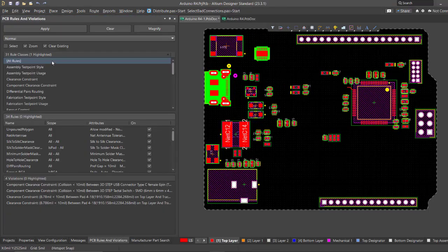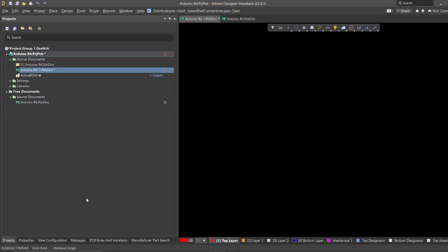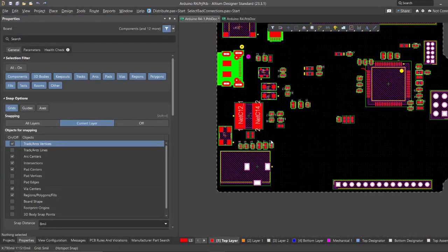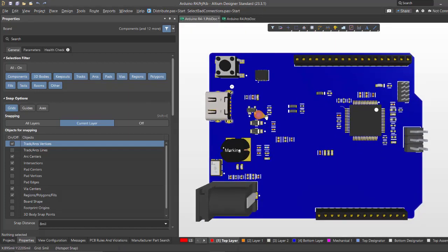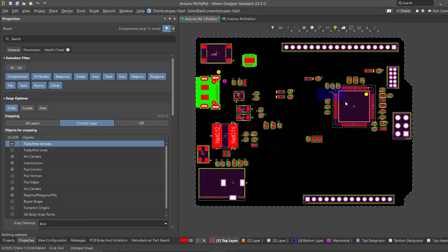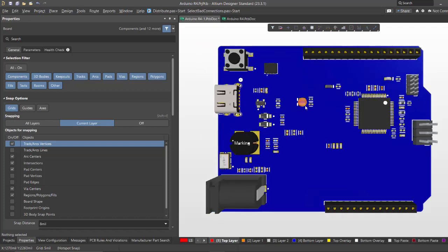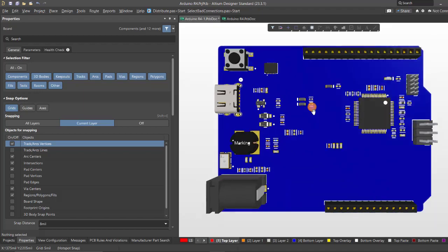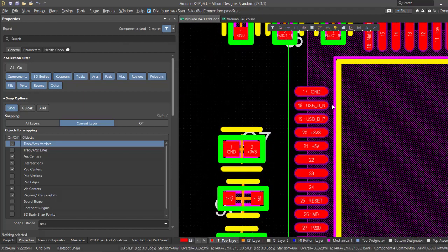Next, we need to add a via fan-out in the components. Adding a via fan-out is crucial for efficient signal routing in PCBs with components featuring a high pin count. It simplifies the routing process, reducing congestion on the top and bottom layer of the board. This not only aids in completing the design but also enhances signal integrity by providing shorter and more direct pathways for traces. So, to add a via fan-out, first, place a track.